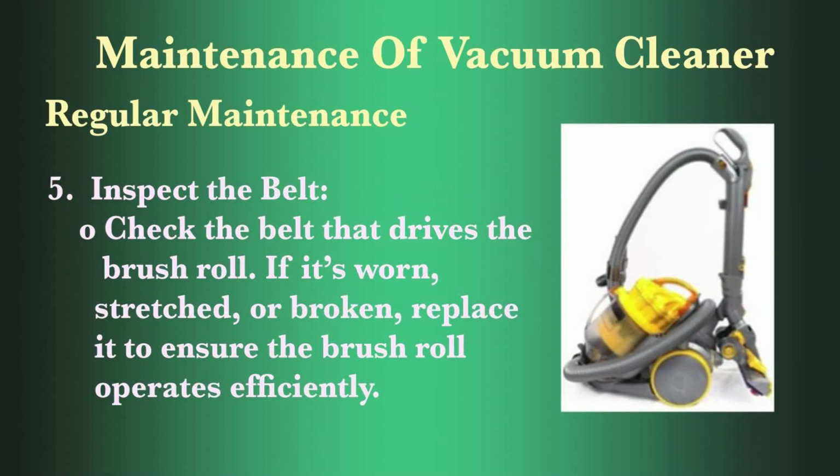Then number 5 is you have to inspect the belt of the vacuum cleaner. Check the belt that drives the brush roll. If it is worn, stretched or broken, replace it to ensure the brush roll operates efficiently.